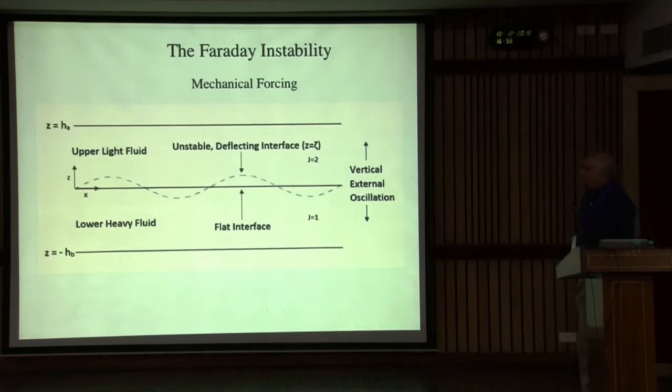And if there was no viscosity, you would just get a permanent periodic motion of this going up and down. The frequency of that motion is the natural frequency for an inviscid layer. If you have viscosity, you will see a decay of that. And in the last gasp, as it's coming down to its end, that would be what we would consider the natural frequency, something that you can calculate from the eigenvalues of the perturbation of a fluid layer.